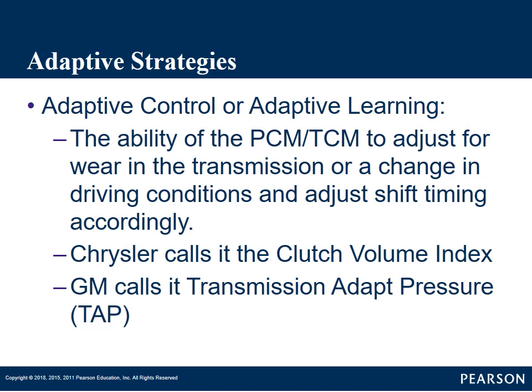Wear in clutch packs or bands would mean they take longer for that clutch pack to apply. Wear in a pump, to where it takes more to build that pressure up. All right. All these could be wear that the transmission has to account for, adjusting that shift timing or pressure, so we can get it back to where it was programmed to be.